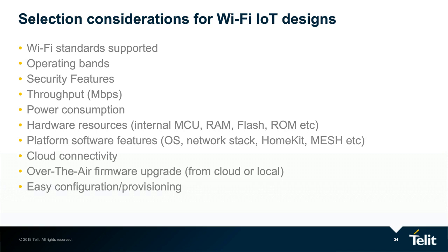People believe it is very easy to make this decision and get carried away with the fact that 11AC provides high bandwidth. But a designer should understand that the coverage of AC is significantly less than BGN. By coverage, I mean the range. Also it's power hungry, so if your product is expected to operate on battery, it will drain out pretty quickly. So what I'm trying to say is that you make an informed decision based on the product use case.